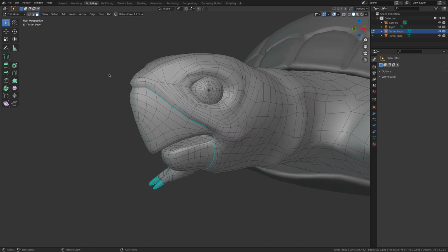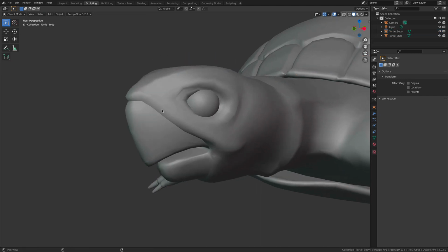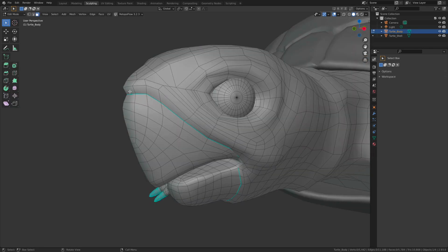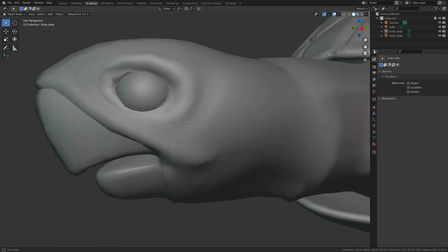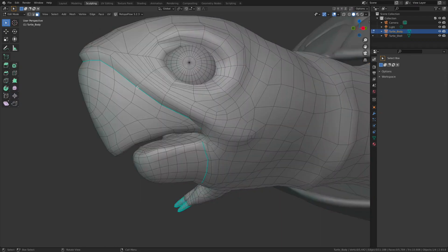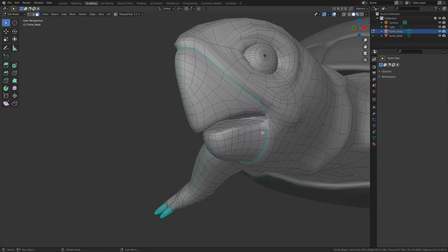And the reason I did that, let's just jump over into object mode, is to stop the smoothing of all these polygons right at this edge. If you look geometrically here, it's just a single line, but because of that smoothing group, because that hard edge is stopping the smoothing system to conclude and start again when it reaches that edge, we get a real nice separation between all these points. And here inside of Blender, those hard edge tags are displayed as these blue lines.